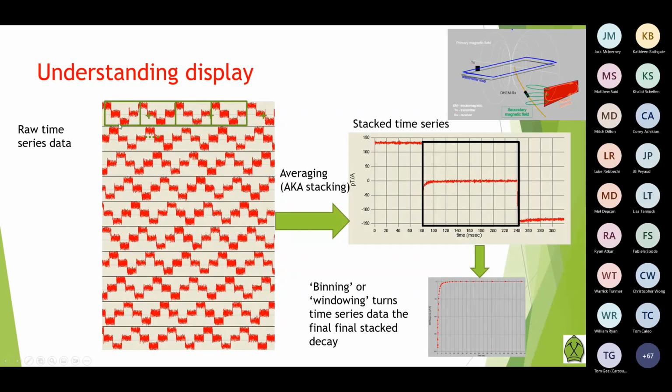If we did 4 of these in 1 second, that'll be a transmitter frequency of 1 hertz. So each of the on time, 250 milliseconds, 250 milliseconds, 250 milliseconds, that's 1 hertz. So that's the frequency right there. It depends on the amount of time that takes to do one of these.